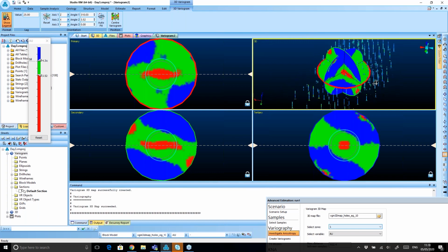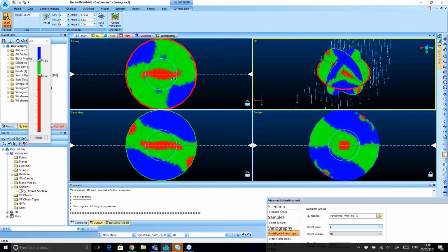Yeah, and now you can see I can check. If I check here, you can see my 3D is everything is moving there as well. Let's use that 305 or 310 for my angle. But also what you can do, either you can change here, or for example, you already know the azimuth and dip of the mineralization of your ore body, you can type yourself here. Just type from your keyboard, click here and then type. Let's say for example 310, enter.